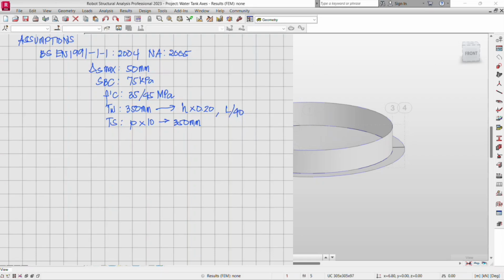All of the geotechnical input should come from the geotechnical engineer. There should be a soil report on that. But in case there is no soil report, we need an input for the Kz. I do have an approximation, but usually it's just an approximation. If you don't have the Kz, but you have the maximum soil bearing capacity of 75 kilopascal, for example, I usually use a rule that most engineers use: it's 120 multiplied by the soil bearing capacity.